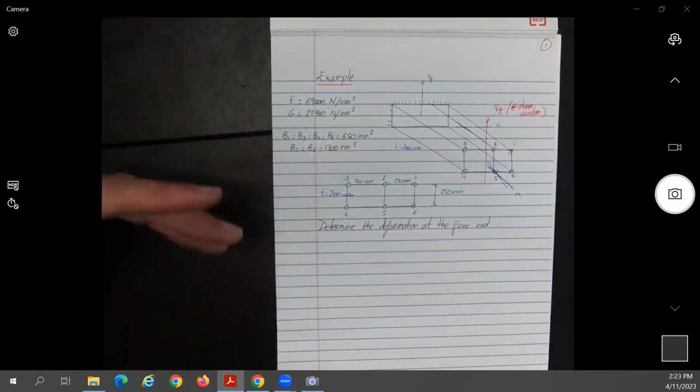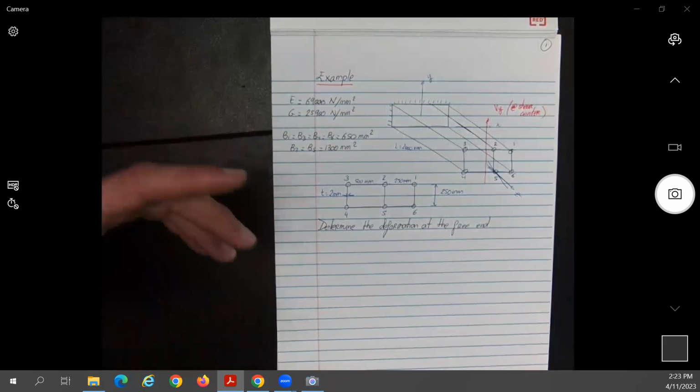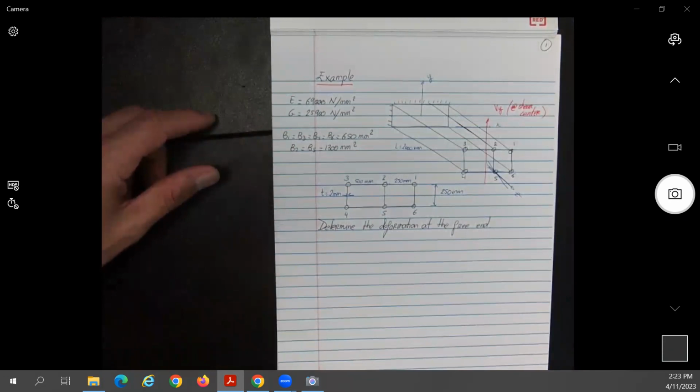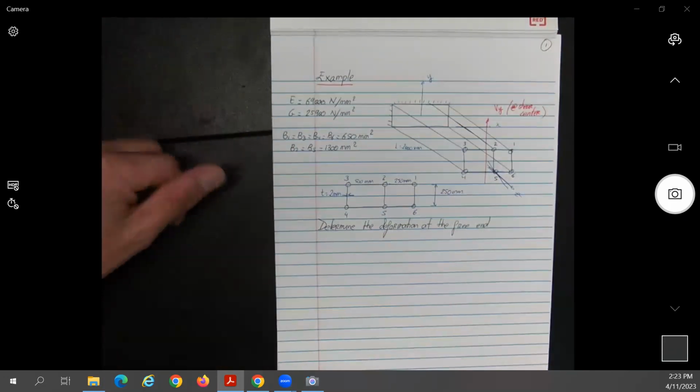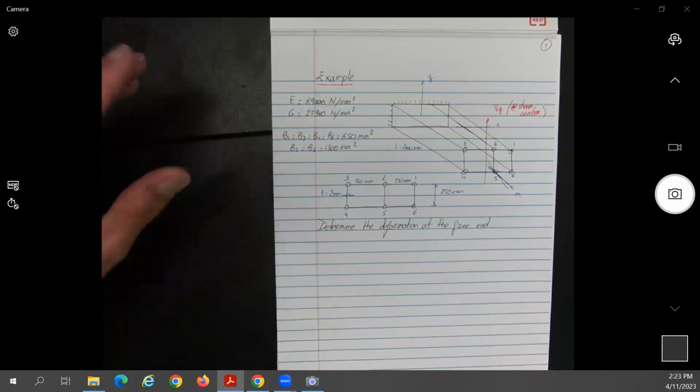Okay, so this is a problem that is not new to you, no? Except that what we need to find is the deformation instead of the shear force, but it's exactly the same thing. So they mention in this problem that the Vy force is applied at the shear center. What does that imply? Anyone? There's no moment. Correct. In this case, the moment is really the torque.